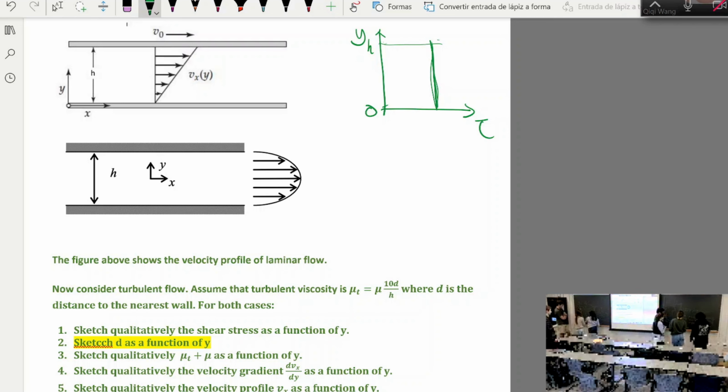All right. So basically, near the wall you have steep gradients, right? In the middle, where you have large viscosity, you have a lot shallower gradients. Everything you see in turbulent flow is like that. Near the wall you have steeper gradients. Away from the wall you have shallower gradients. Compared to laminar flow, it's always the case. Yeah, this is good. This is also good.